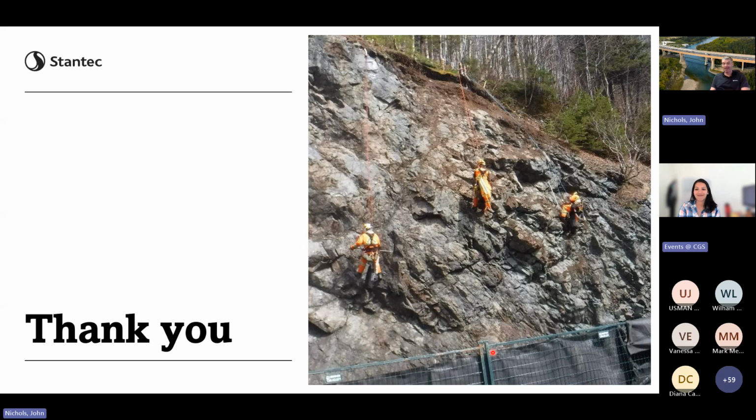Yes. So often my first reflex is, if it fits together perfectly right out of the core box, and you can't really see anything, then it's probably mechanical. You can often see rough, kind of unnatural surfaces in that break. Another feature of an artificial break that I didn't really get into is called disking. If there are stresses locked in the rock mass and you de-stress it, the rock may disc. That's another artificial feature of the rock mass that you'll see.